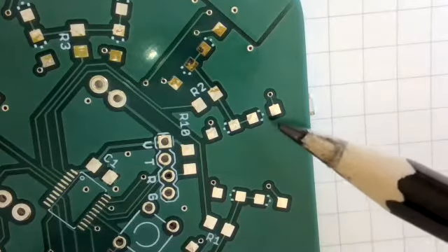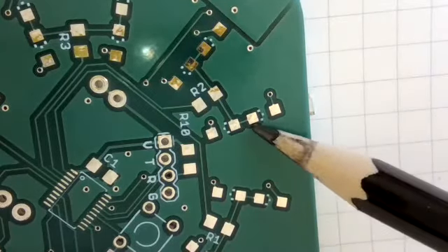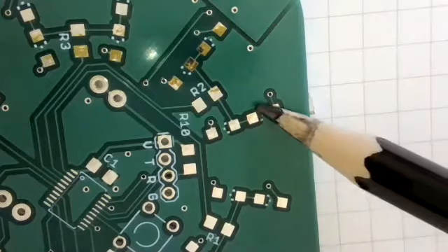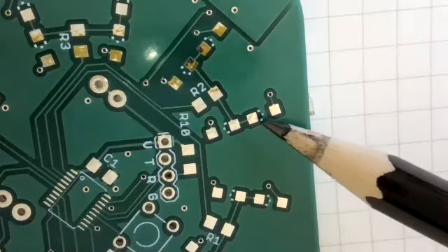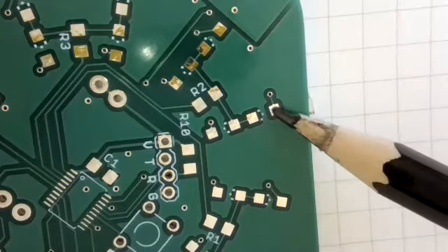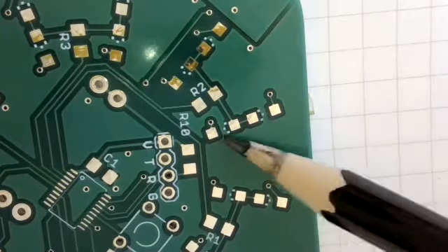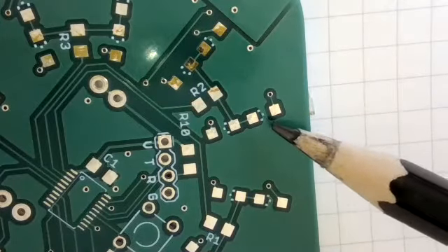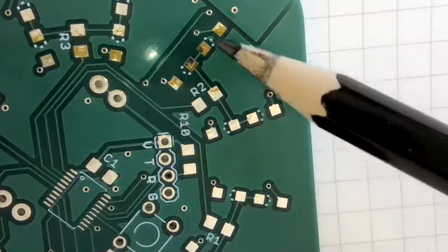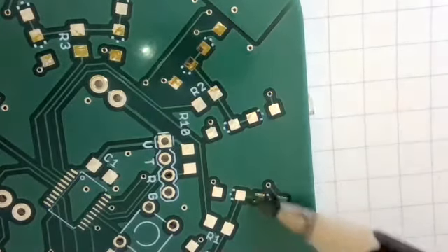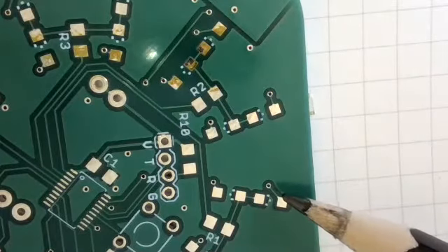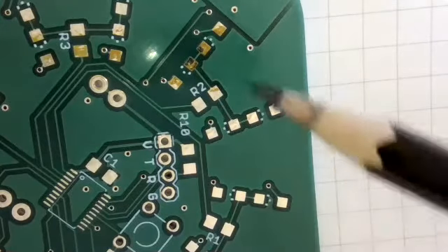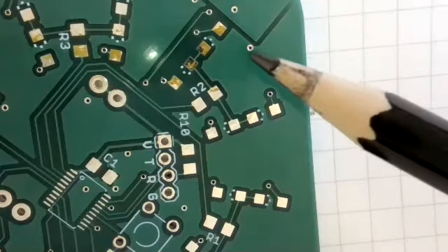But okay, in order to put your diodes on correctly, you need to have the proper direction of pins. Now, the arrow is drawn this way, right? So ideally you would line it up that way, from anode to cathode, but you don't have to. In principle, you could also do it exactly the opposite for all of them, in which case the control would be reversed. But if you don't do it the same for each bank, right? So this LED and this LED are both being controlled by the same cathode pin. If you do it opposite for these two, then things won't work, right? So you really want to make sure that you know which direction your diodes are supposed to be pointing.